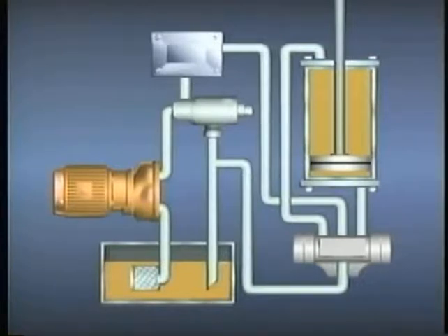During operation, hydraulic fluid first passes through this strainer on the pump inlet line. The strainer traps small particles and prevents them from entering the pump and causing damage as fluid continues through the line to the pump. The pump's basic function is to convert mechanical power into hydraulic power by applying force to the fluid and moving it through the system.